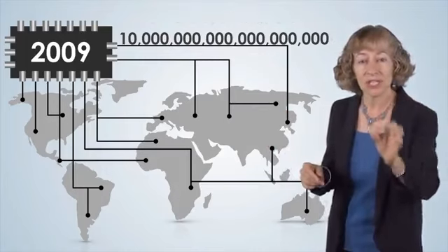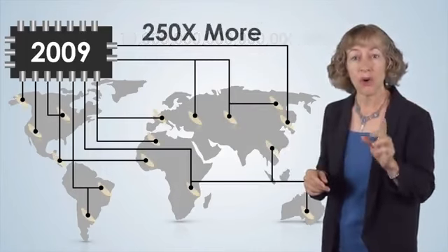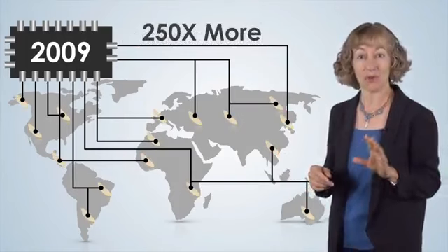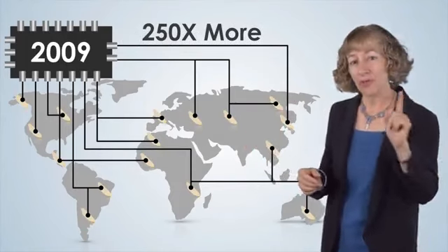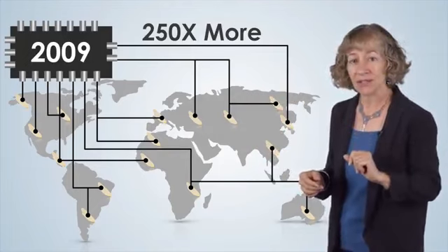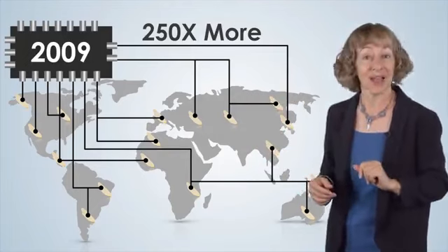Those 10 quintillion transistors are 250 times the number of grains of rice that were eaten worldwide that year. And for the price to produce a single grain of rice, we can produce 125,000 transistors. These integrated circuits are made with thin materials that we deposit, pattern, and etch, and they're materials such as metals and dielectrics. The machines that perform these nanofabrication steps are the focus of the nanofabrication videos in this course.